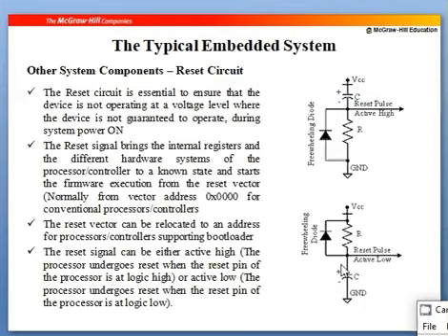So understand when you are going to reset the sequence. When the signal is active low for a small duration based on RC, you're going to reset the sequence.